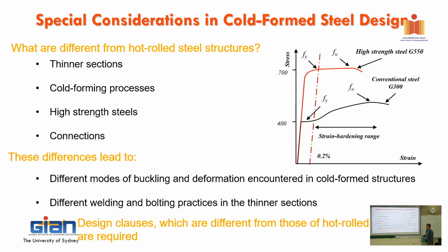And that's why we need to have special design rules. That's why in Australia we have a separate design standard for cold formed steel. If you use hot rolled steel rules to design a cold formed steel structure, it's not going to be appropriate. So we need to, yes.